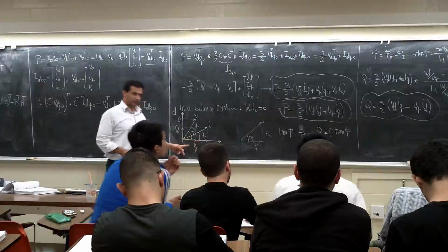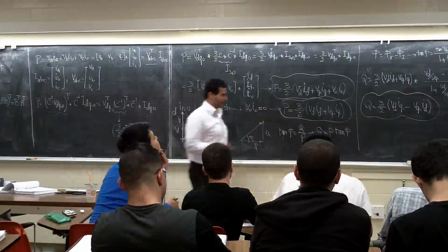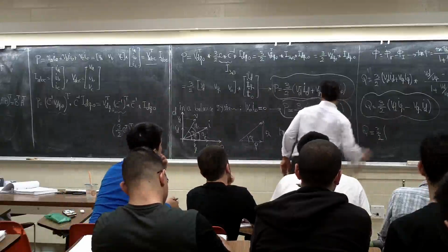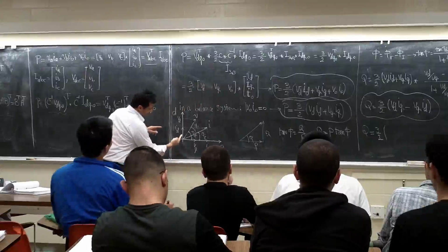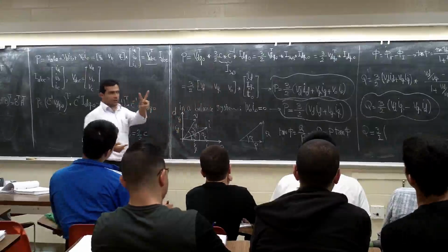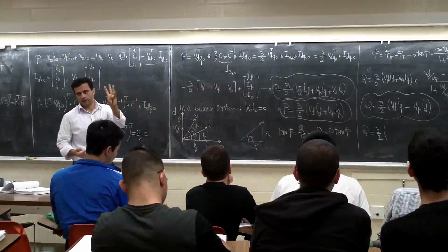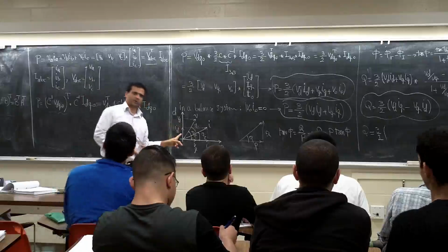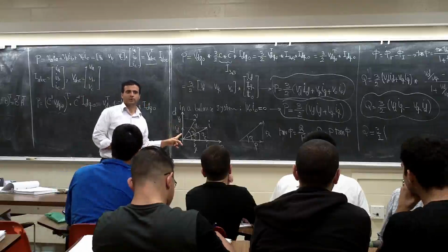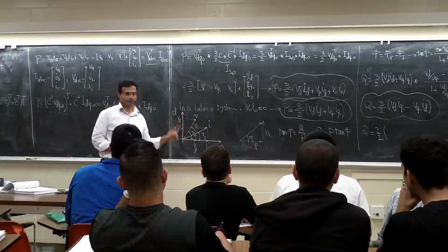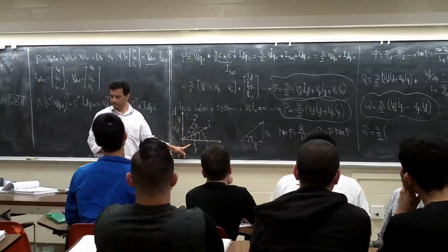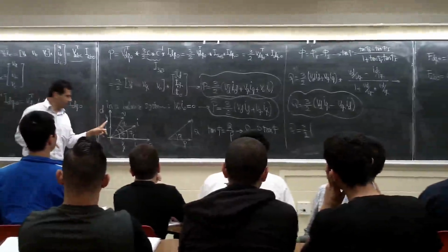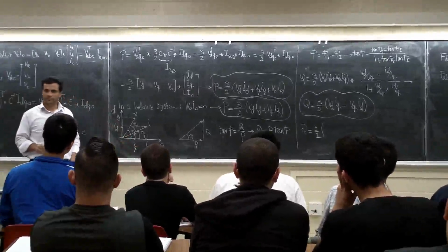One easy way, let's say it quickly. I'm going to just look at this value, Q. This 3 over 2 is going to be here, but look at this term. I have two voltages, Vd and Vq, and two currents, Id, Iq. How much reactive power are they going to generate? Vd and Id: they are in phase, so zero. How about Vq, Iq? Zero. So two of them are gone. How about Vd, Iq? How much reactive power?